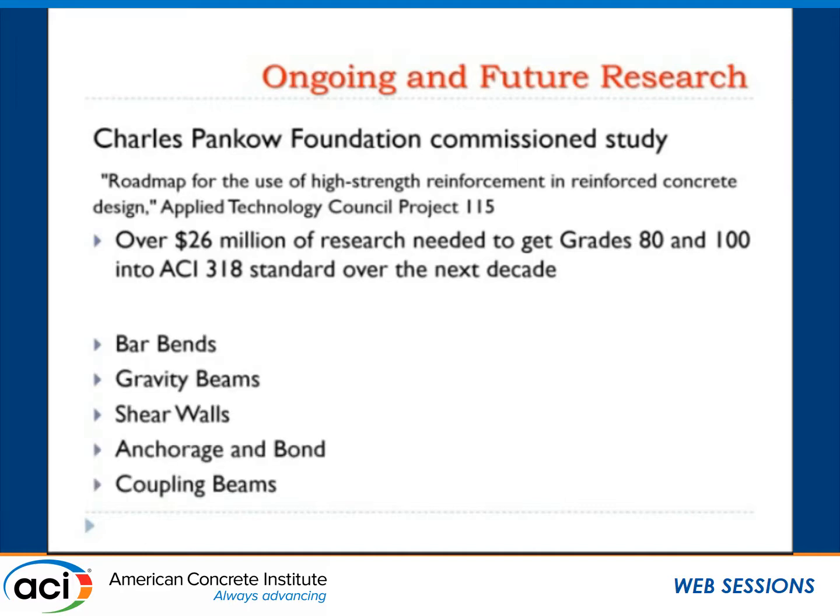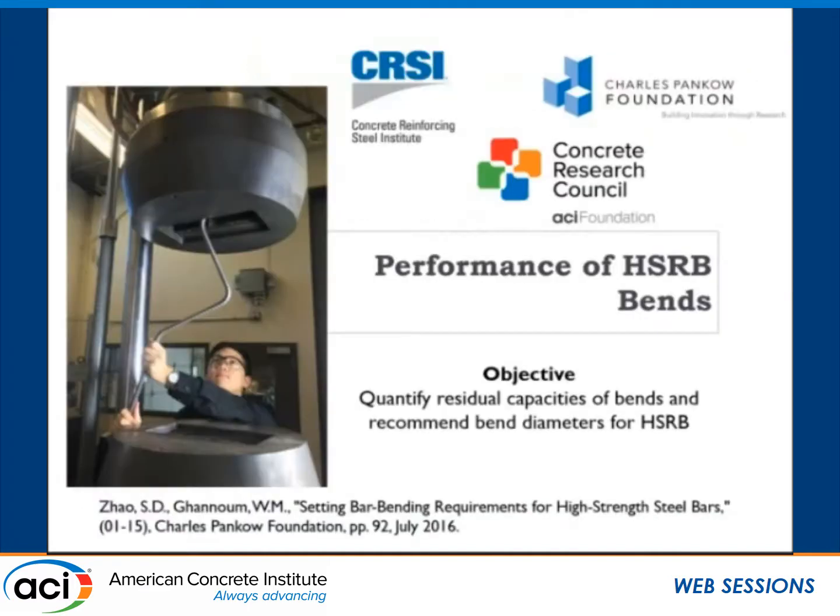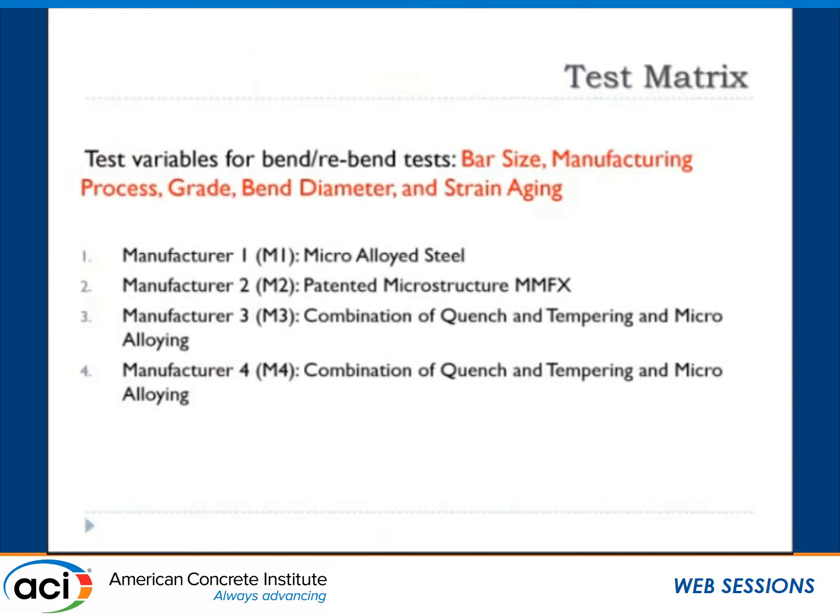And I'll touch on a few topics of interest, looking at some bar bends. The steel is more brittle, so it maybe needs wider bends. Then gravity beams, shear walls, anchorage and bond, and coupling beams just started, so I don't have much on these, but I'm going to highlight a bit of research that's being done. So, performance of bends, looking at what the bend diameters are. I'm not going to get into the details of this one. This is a study that was completed last year. We looked at also kind of the main 4